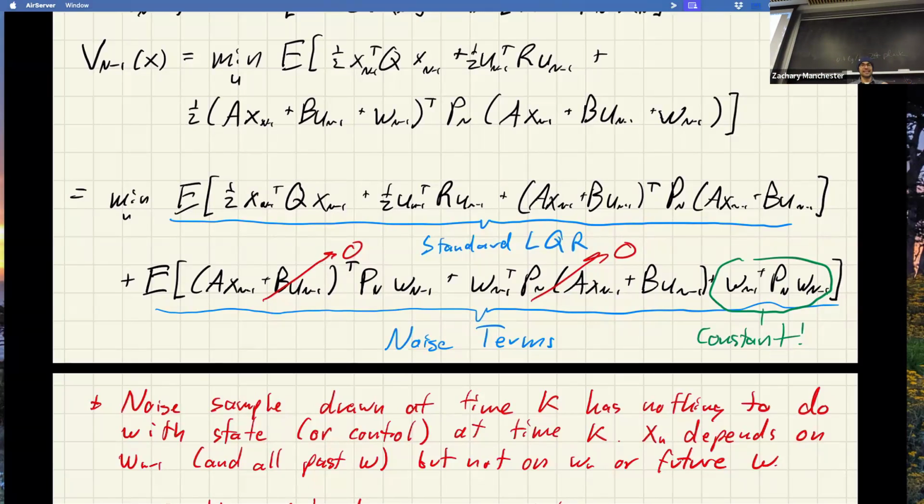So that's the context in which that idea is very pervasive, and it's really deeply tied up in how we smush control problems into this LQG setting. Kind of the idea is you should model everything you can. If there's something that's not zero mean Gaussian in there, it could be as simple as it's biased up with some mean. It could be complicated where there's some time varying bias dynamics going on in there. You should do your best possible job trying to model that out. And after you subtract off all that stuff and put it in the dynamics, what's left should basically be white noise. And if you can get to that point, then this is the answer. But to get to that point, you often have to do a good job of trying to eke out every last little thing that's kind of deterministic in there, right?